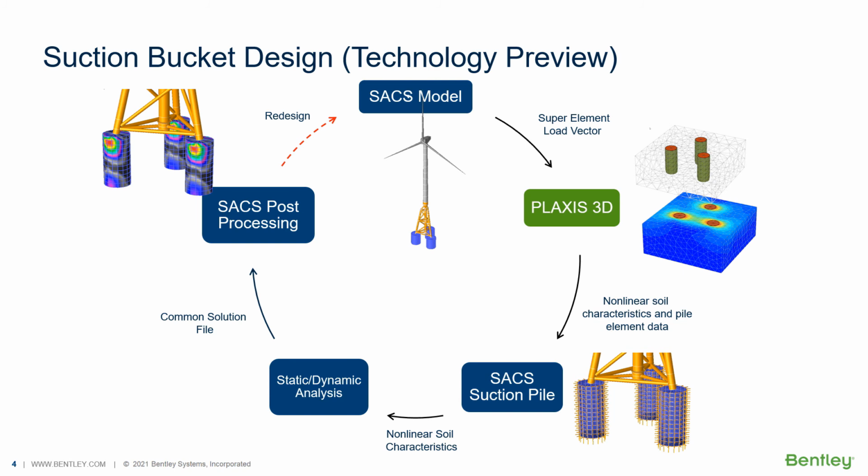The workflow is, first, the user can model a superstructure like a jacket with a series of load cases to generate nonlinear springs. Then we can reduce this modeled system for use in Plaxis. What I mean by reduced model is a stiffness matrix and force vectors.